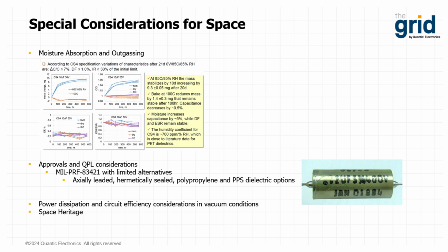One proposed MLP solution using a high temperature, ultra high Q dielectric actually came out with a DF of 0.08% at 1 kilohertz and maintained the operating temperature requirement that our customer was looking for of -55 to +125C in a vacuum. And the ceramics that they were investigating simply could not do that due to their heat output. So I can imagine that any high reliability, mobile, battery powered application that cares about weight and size might benefit from those advantages.